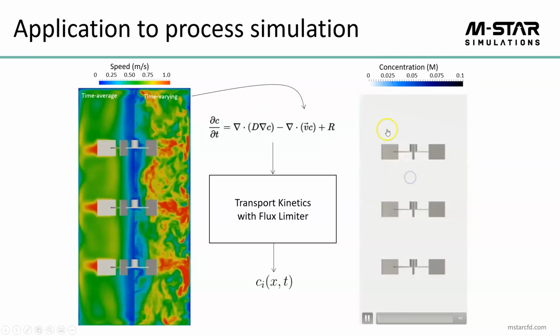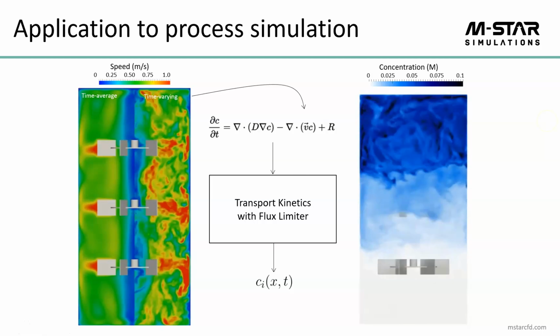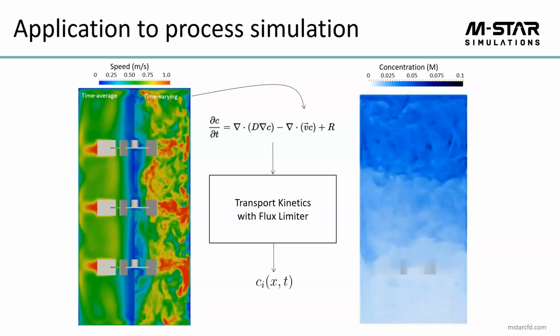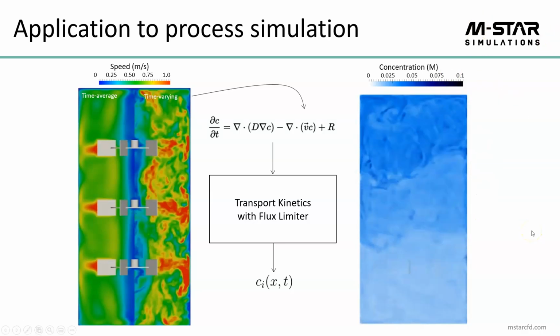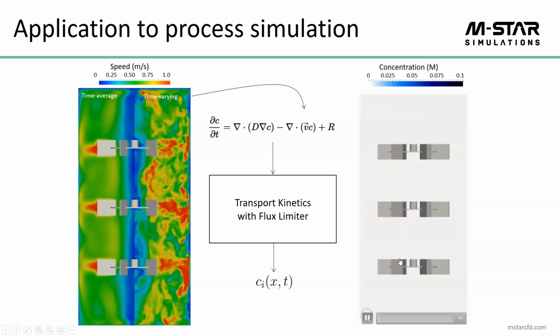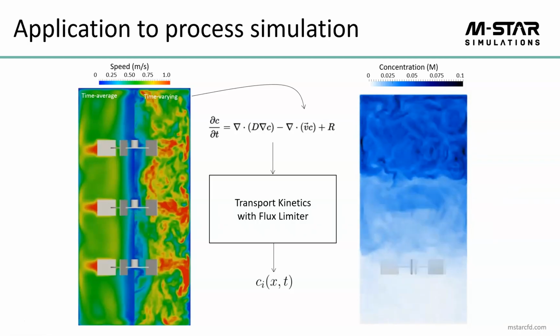So here is me adding dye to the top of the tank to predict a blend time or whatnot. And here I see that competition between the different time and length scales inside the system. It takes a while for this dye to eventually migrate through the tank due to this poor mixing configuration. But here I see those heterogeneous structures coming to bear. I see small structures informing local equilibrium. I see longer term structures informing communication between the two mixing zones. These are the physics we're able to resolve when we have a time varying, time accurate CFD solution.